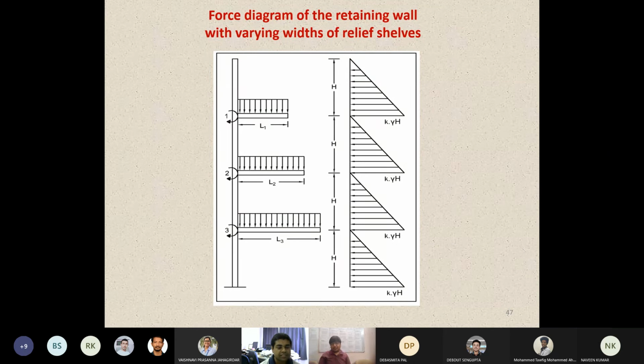Exactly. Actually, I was coming to that point also. Because of the introduction of the relief shelves, which are again semi-rigid RC structures, the intricacies in the reinforcement layout also increase manifold. Now, whether they are doing those things properly or not is another question. So it might not always be just due to the design or the backfilling. The thinner shelves you have and the thinner taper you have, more and more reinforcement gets overlapped and the percentage of steel increases.